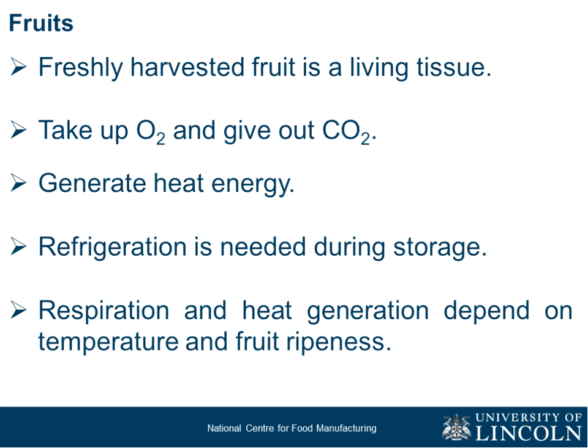So I think I asked a particular question about which one do you think is appropriate for fruit storage? Controlled atmosphere or modified atmosphere packaging, MAP packaging? No, MAP packaging is static. Once you've modified the environment, it's going to be static and you're not changing any gas. But in an environment where the stored fruit is taking up oxygen and giving out CO2, that environment is going to change. So you actually need a dynamic environment to store your fruits.